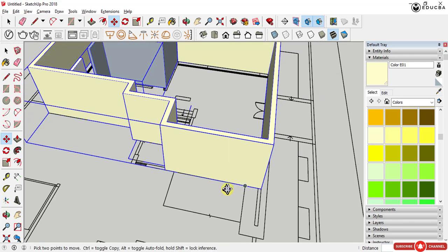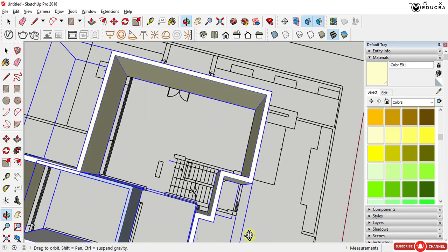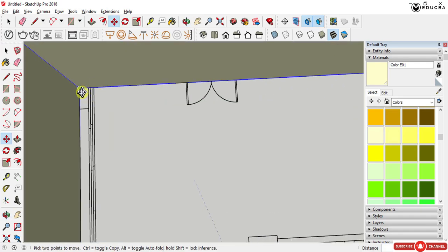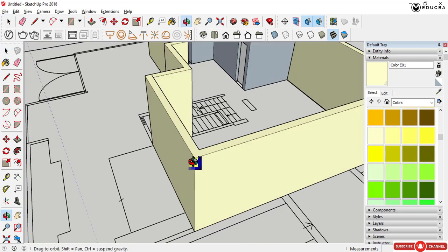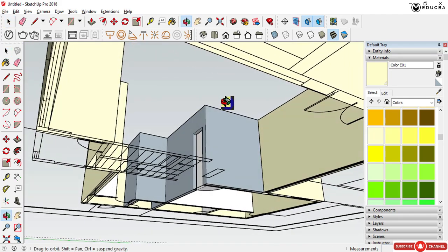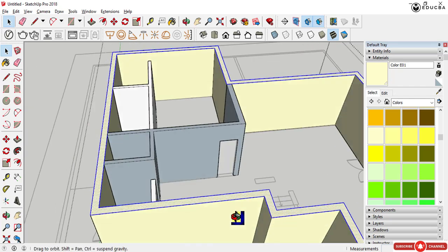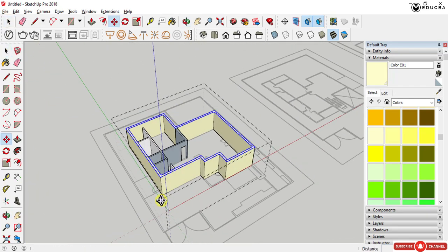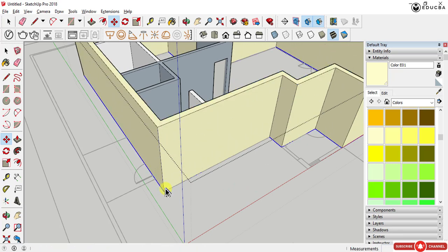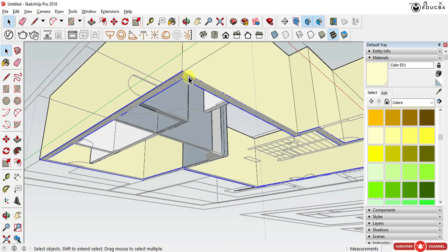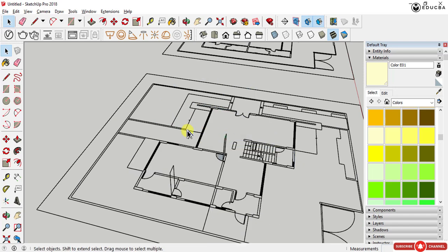You can see we have already tracked. Just place it properly. So after placing the model, we need to have a level or a surface below, which right now we can't see. We're going to go into the group. With a double click, we are going to select the whole surface, and with move and the control command, I'm going to copy everything, paste it below, and also with control C, copy it. Now I come out of the command and with right click hide this particular surface.